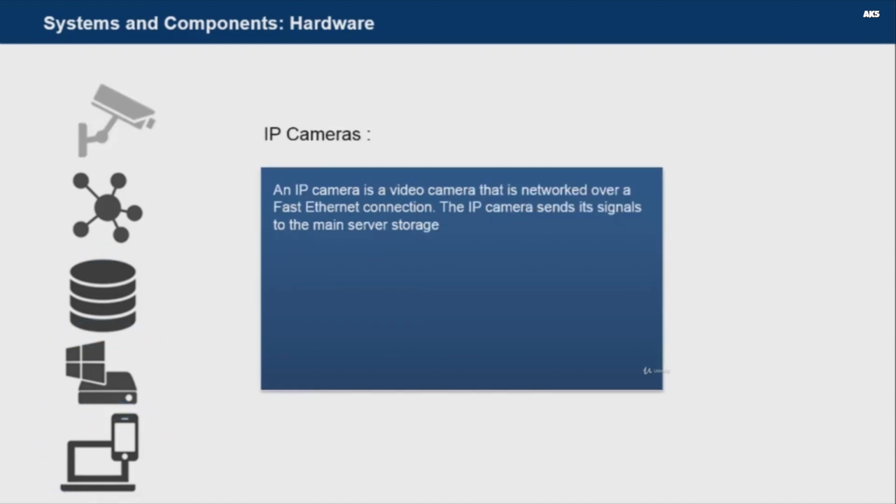First component, as we just saw, is the cameras. This device receives the information and digitally encodes it to video, audio, and other information. It depends, of course, on the type of camera, because some cameras have analytics and then transmit that information over an Ethernet IP network where it can be stored, copied, and added to the database.